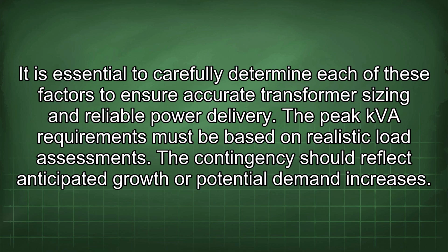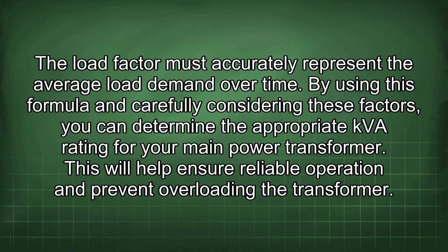The peak KVA requirements must be based on realistic load assessments. The contingency should reflect anticipated growth or potential demand increases. The load factor must accurately represent the average load demand over time. By using this formula and carefully considering these factors, you can determine the appropriate KVA rating for your main power transformer. This will help ensure reliable operation and prevent overloading the transformer.